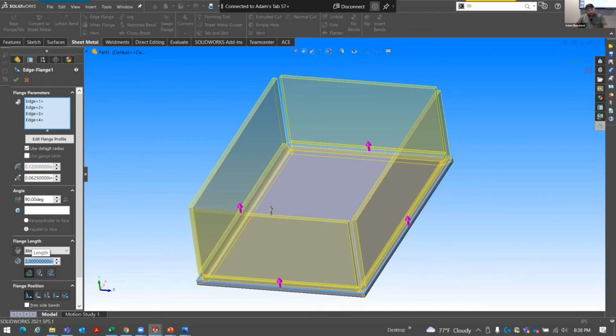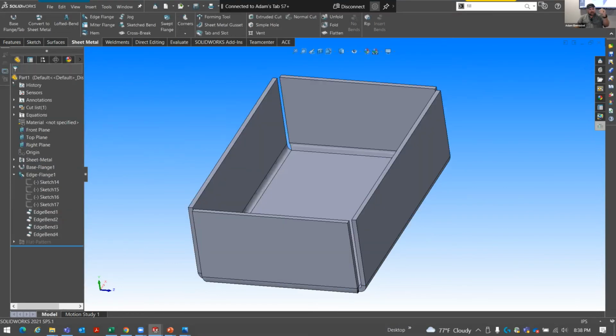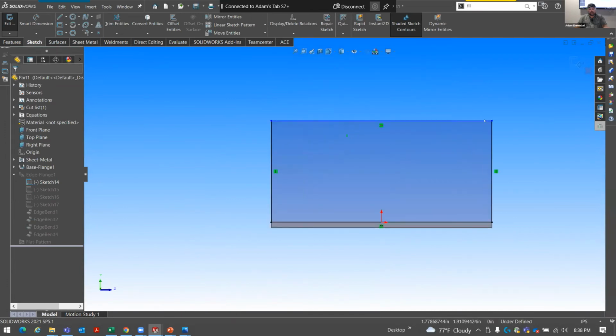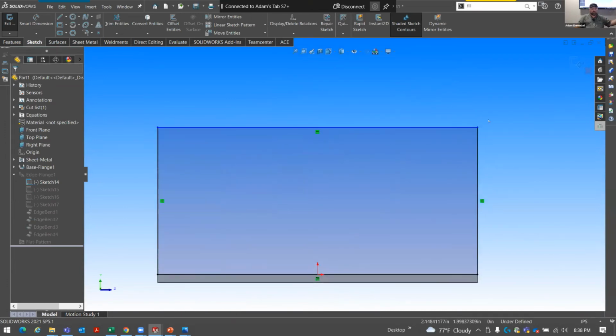All right, and so I'll explain that here just a little bit more. Now we're at 2 inches. The feature itself here, where we edit the feature, is fully defined and it's defining the sketch, but I can come in here and manipulate this sketch independently. Notice we do have a blue line. A blue line means what? Underdefined. What does it tell us down here in this bottom right-hand corner? Underdefined, right? Those are where we double check ourselves, make sure things are fully defined.